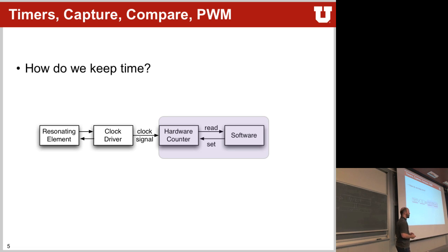Yes? Well, I think what he's asking is, say the timer gets updated on a rising edge of the main clock, and then the capture compare register gets updated on the falling edge of the clock. I don't know how long the propagation delay is on the timer. Hopefully it's less than half a clock. And then the capture compare register is just like a D flip-flop where you tell it to sample, but it won't happen until the next clock. Yes. Okay. So that might fix it. Yes. That's probably oftentimes how they implement the synchronization bits.